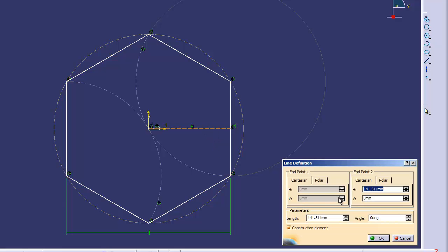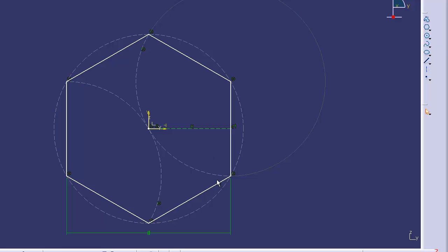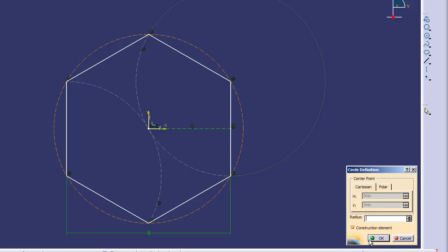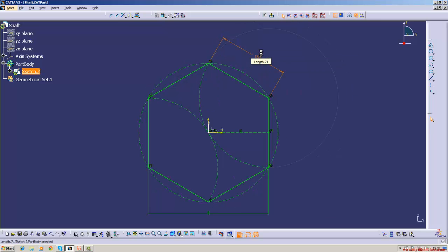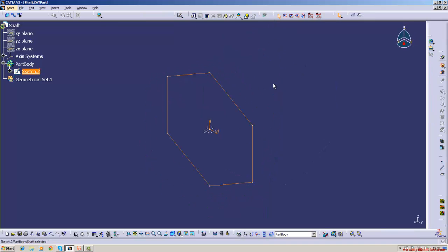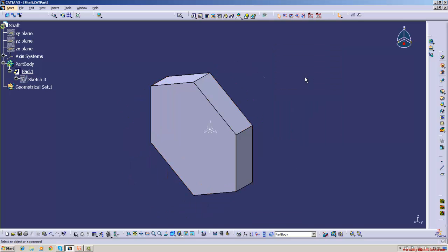This distance you can have 150. This you can't change. Radius will say 150. This dimension we will dimension, we'll see. 150. Okay. This side is 150. So this is a hex head. We use the pad command to make a head. So the head about say 50 long, an exaggerated value I'm taking. And suppose we create a hex bolt, let us say. Create this.